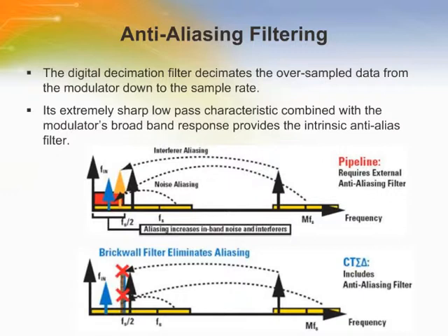Because the CT sigma delta analog to digital converter samples at the output of the forward loop filter, the signal is first low-pass filtered by the loop before sampling, which attenuates signals around the modulator loop sampling rate that can alias down in band. Furthermore, because these aliased signals are then injected at the input of the internal quantizer, they are noise-shaped by the loop in the same manner quantization noise is shaped.